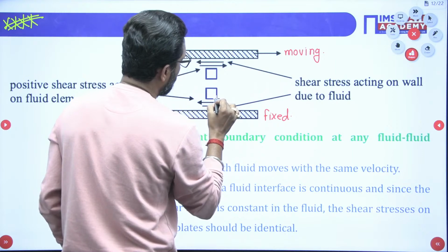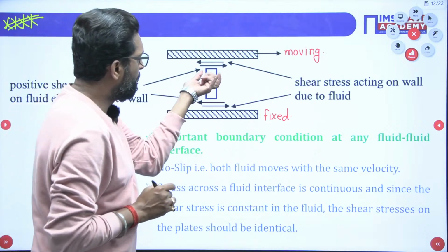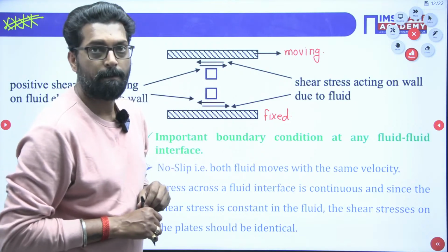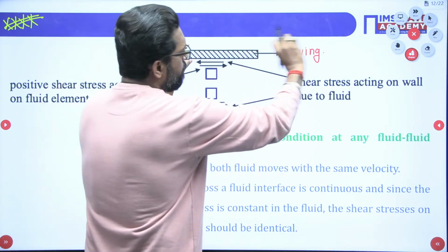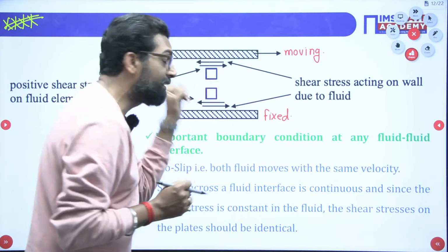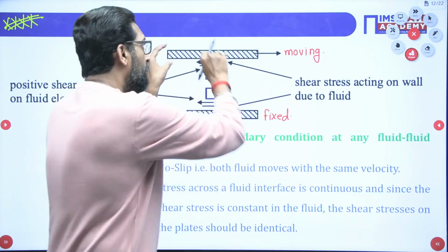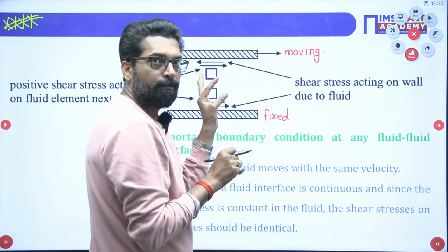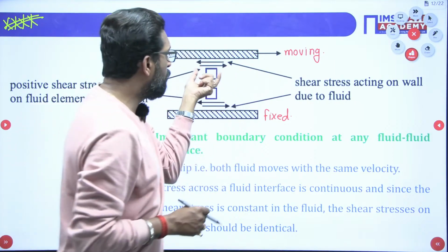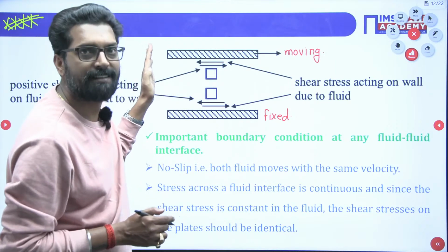Please listen very carefully, I am telling you, beta. This fluid element is nearer to the moving plate, and this fluid element is nearer to the bottom plate. Now, if the plate is moving in the right side direction, yes, it is in X direction, please listen very carefully. Many teachers also get confused here. If the plate is moving in a right side direction, then on the plate, the fluid will exert left side shear stress. Left side shear stress.